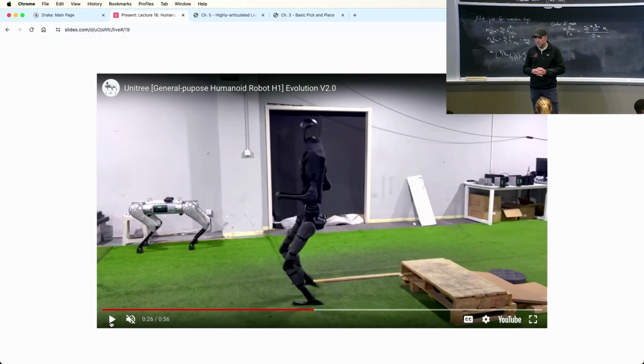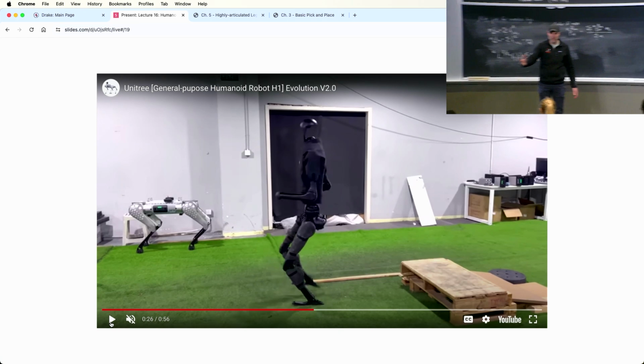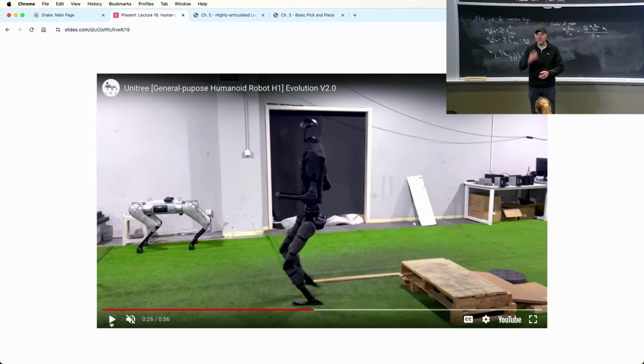But just appreciate how diverse and general purpose the ZMP walking is, right? It's one thing to have a policy that walks straight, but if you have any new situation that you want to navigate through, it's pretty easy to write a footstep planner, and you can close the loop. To do a completely environmentally goal-conditioned policy in RL that does everything, that's a much bigger ask, right? So it's not just find a nominal limit cycle. It's conditioned on all the task-related variables. Yeah. Did you have a question back there?